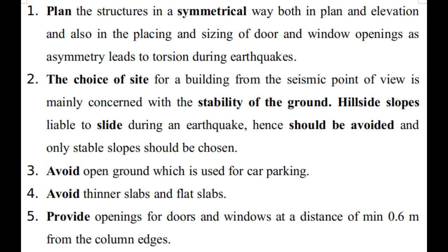So first point is the structure should be symmetrical, doors and windows size should be symmetrical, their placing should also be symmetrical. This is the first point, because asymmetry leads to torsion while earthquake occurs.